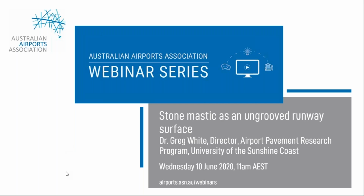One, because it'll just provide a nice sound hard base to put the SMA on. It'll also take out any roughness in the underlying base course and essentially provide a nice smooth surface that doesn't require any shape correction.